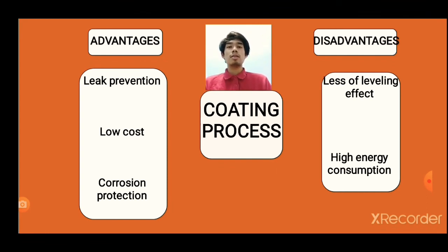The first disadvantage is less leveling effect. It means that the powder coating that we use for our product has less leveling than paint. It can easily create messy hills and valleys on our product surface, which is not a good finishing.